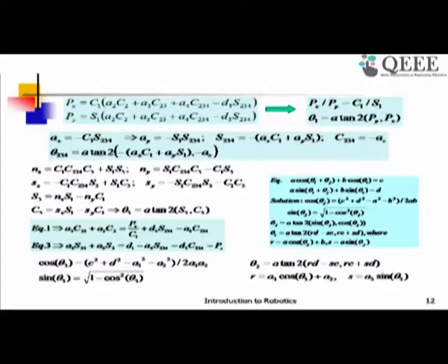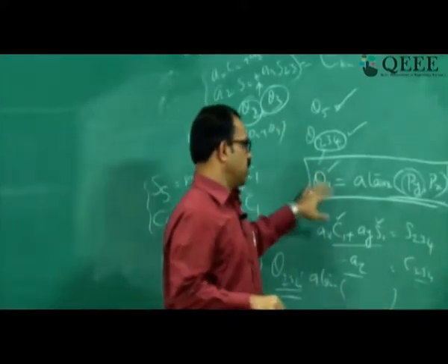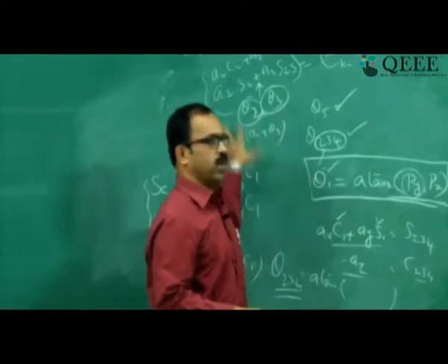It may appear slightly complex, because solving the equations is the challenge in inverse kinematics. What we need to do is look at the 12 equations and try to find similarities or a trick to solve them, find whatever possible ways of solving the problem, and then solve using standard trigonometric relationships to get theta 1 to theta n, depending on the number of degrees of freedom.